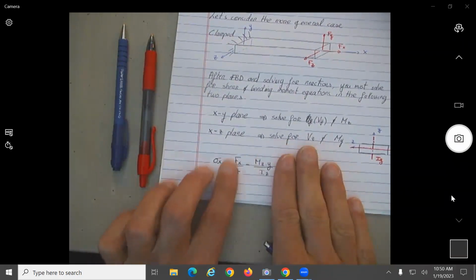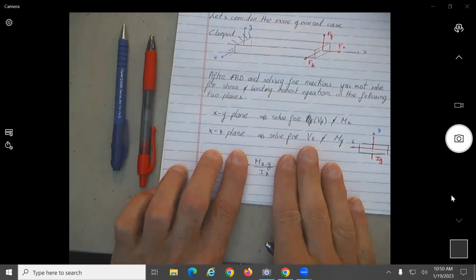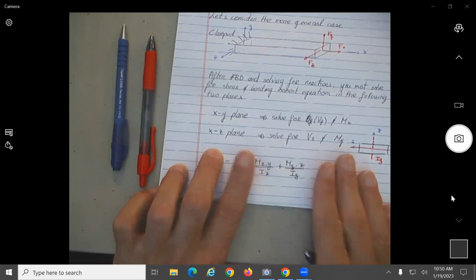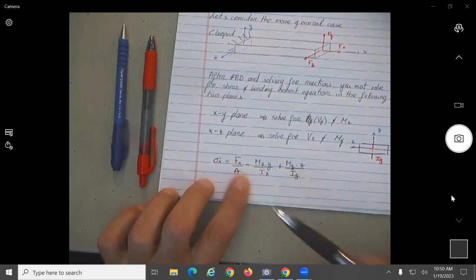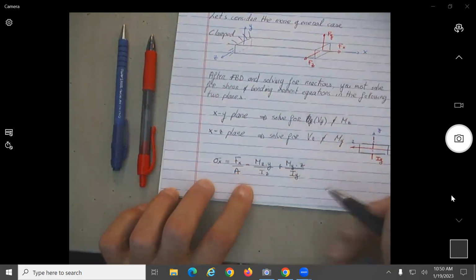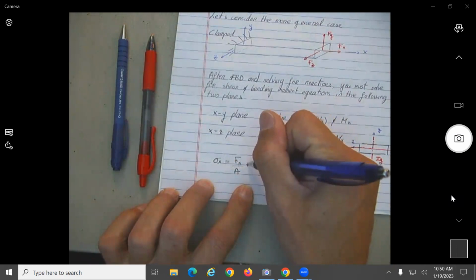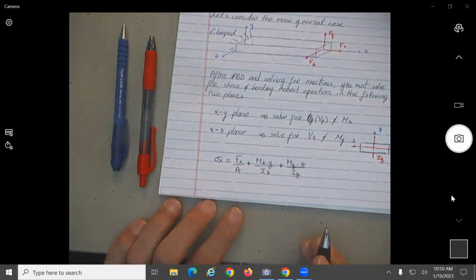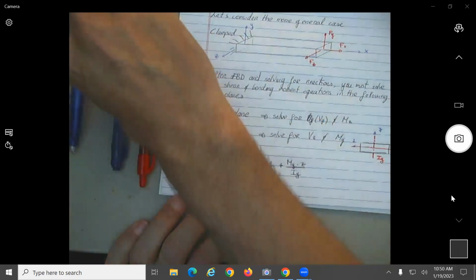How are you going to figure out the sign of this one? By figuring out if the location is in tension or compression. And this one, the same thing. So even though in books generally they will give you this because it's what the moment will induce, I'd rather just put positive on everything and you get the sign from understanding.